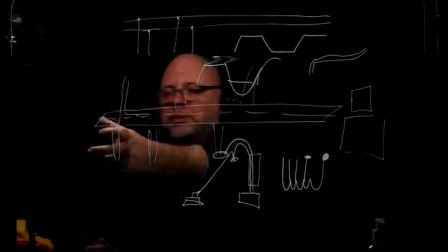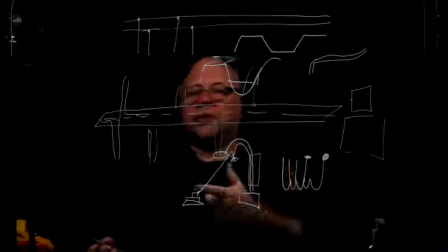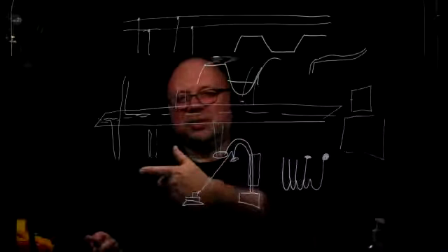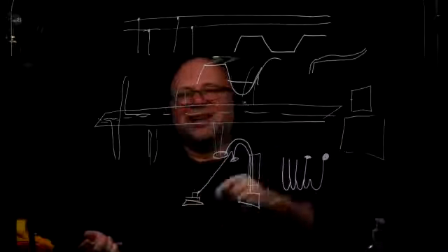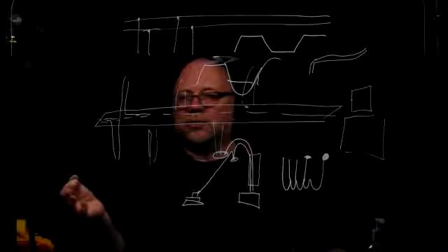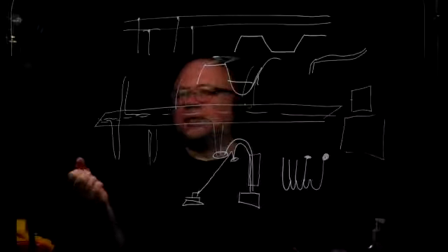You're sending a DC signal to a coil, because speakers have coils, and the coil is going to conduct a DC signal just like a 0-ohm resistor. It's just going to pass through a lot of current through the coil that it's not supposed to, and that can heat up too much and burn out.